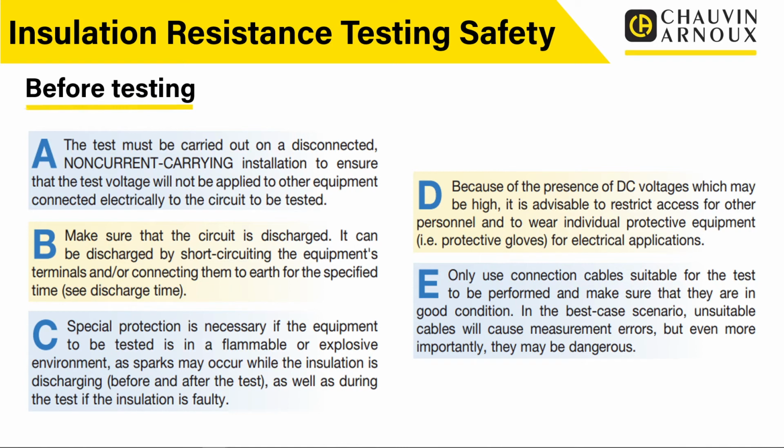So you do need to be very, very, very careful when you're applying an insulation resistance test that you are in control of the whole test area and you've considered the full implications all the way through the installation for you actually carrying out that test. So there's a few pointers here that we're just going to go through, really just to give you some ideas of what we should do before we carry out insulation resistance testing.